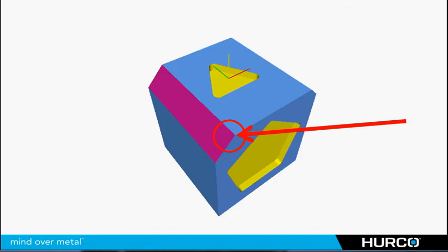Just like the other side, I'm going to move to a corner of the feature, pretty much the same corner that I did on the other chamfer, only on the left side of the part. So this time my origin point in X is going to be a negative number. I'm going to put negative 2 inches because I want to put a 1-inch chamfer. I'm going to stay 1 inch shy of that left side of the part. So I'm not going to go the full 3 inches in negative from the center to the left side. I'm going to stop an inch short.